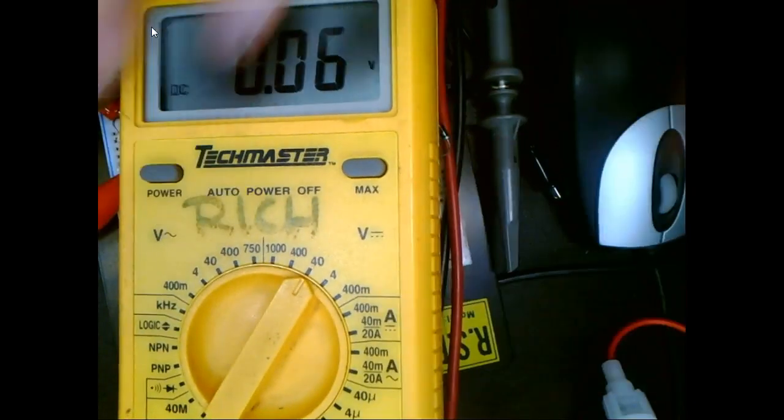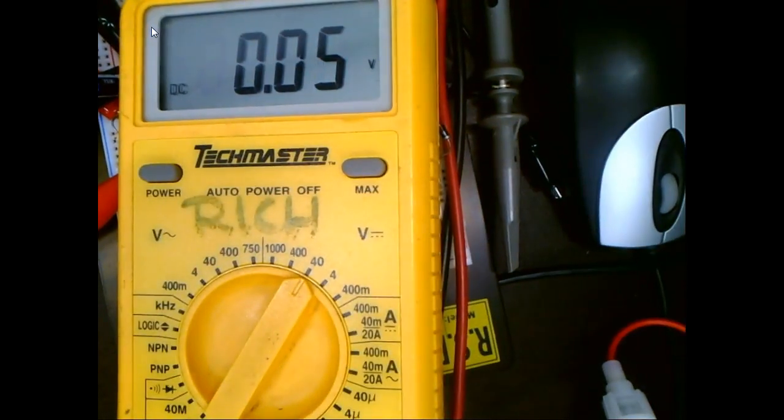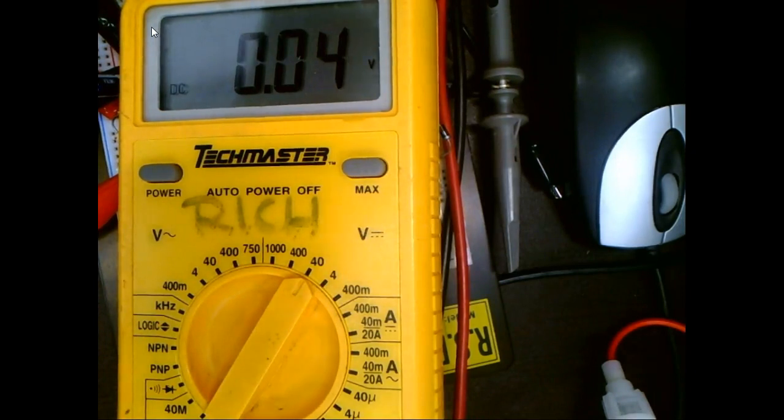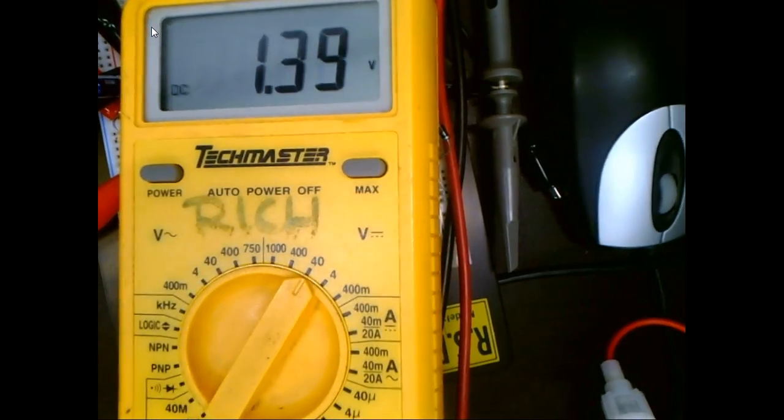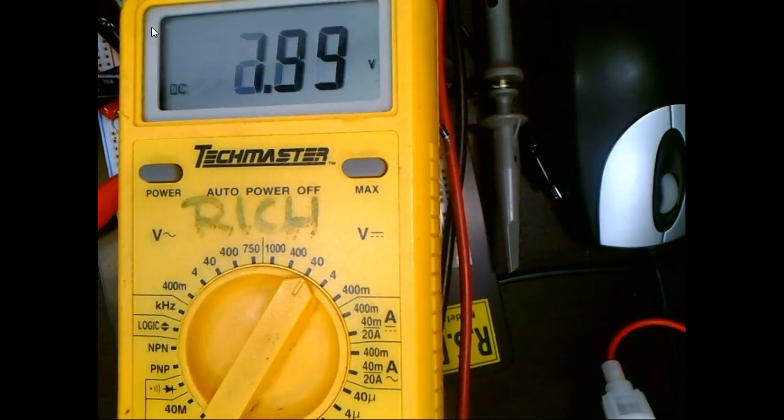And right now, the capacitor is basically discharged. I'm going to turn this on. And what's it doing? Now notice it started out charging real fast. But as the charge goes up, the voltage drop across the resistor goes down, the current goes down, which means it starts charging slower. So the closer it gets to fully charged, this guy's going to charge real slow.